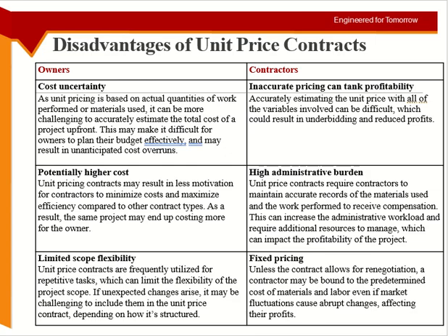Okay, here the unit price is normally used where the things are repetitive. You are doing the same thing again and again. Okay, so in many cases this will not work. For example, for small projects, this will not work, because for small projects you want to just have a total cost. Okay, in big projects, then you can go for this type of contracts. Okay, yeah, the pricing is fixed. The unit rate in this case is fixed.